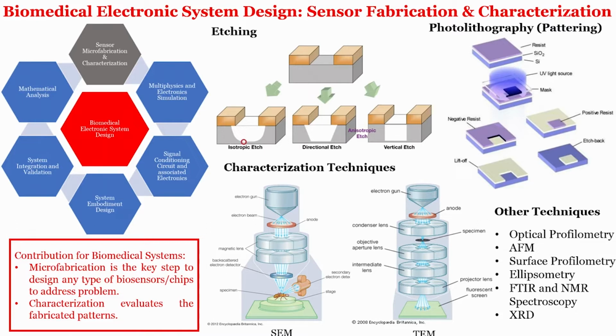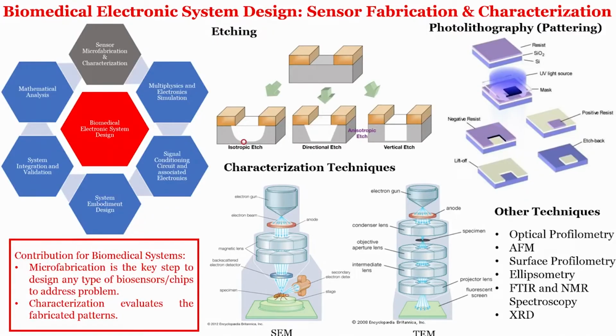That is why when you say electronic system design and mathematical aspects, what is within the electronic system design are sensors, and that is why, after discussing with Professor Chandramani, who is leading the course, we wanted to see how sensor design and lithography could help to understand the whole concept correctly. And that is why, if you see the slide once again, the lithography which is patterning has photolithography, E-beam lithography, X-ray lithography, and then there are techniques like DRIE or wet etching.